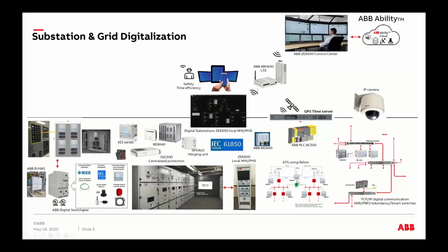You could utilize the digital relays nowadays. Digital relays can do some PLC functions for you. For example, you could be thinking of doing an ATS scheme using the relay instead of having an outside device. So there are many things you're going to start thinking about when you start doing these brownfield projects.